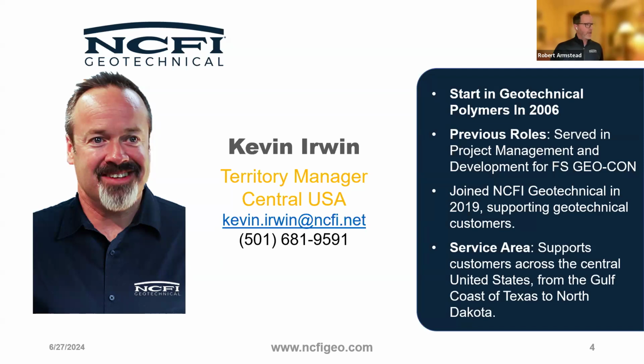So we've got: how do you install injection tubing? If jetting, can you jet them into dense, stiff soils? Do you abandon them by grouting them in at the end? You can jet. That's real handy in sandy soil types like you find down in the Houston, Texas area, where I grew up. Jetting with water is useful. Yes, you can grout them back in place.